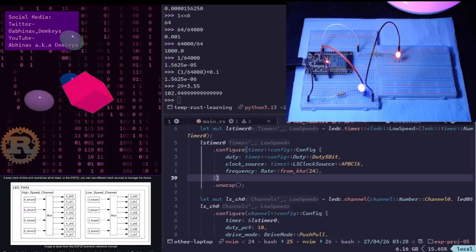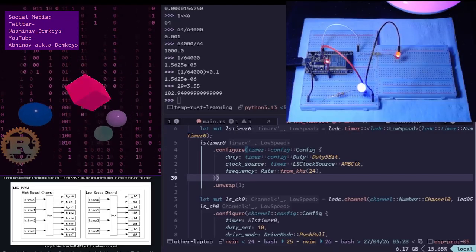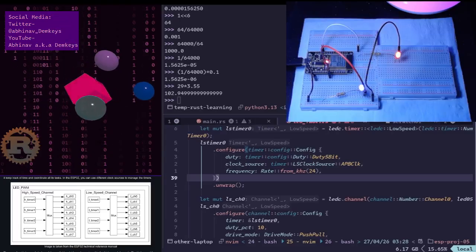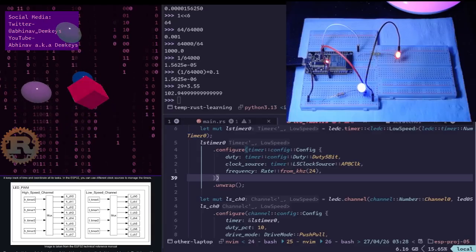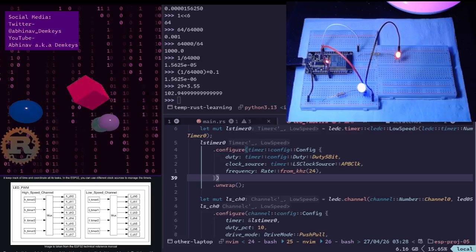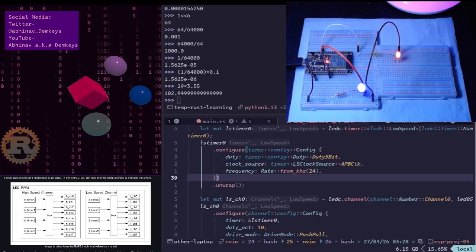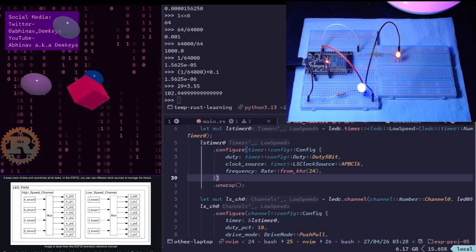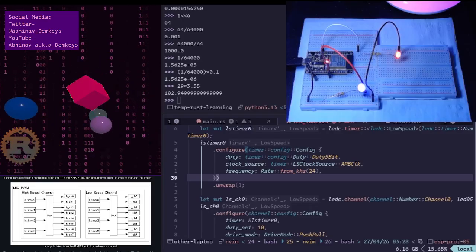You can program the PWM, which I'm assuming happens through setting registers, to behave a certain way, and then it's just going to keep doing its thing while the CPU goes to sleep. The PWM is running, which consumes considerably less power than whatever the CPU was going to siphon out of your battery.